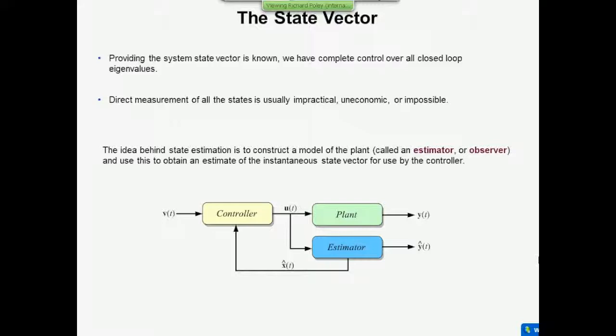And this is the job of an algorithm, which is variously called an estimator or an observer. They're exactly the same thing, it's just that different people give them different names. And because I feel that the term estimator is more descriptive of what it actually does, I'm going to call it an estimator. This is how it fits into the control loop. I've described the controller, which consists of the gain matrix K, the input matrix N, and possibly an integrator or a series of integrators. And that involved the input, the feedback state X, and it outputs the control effort U.